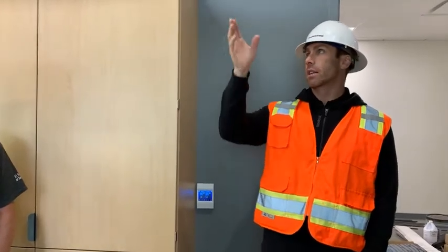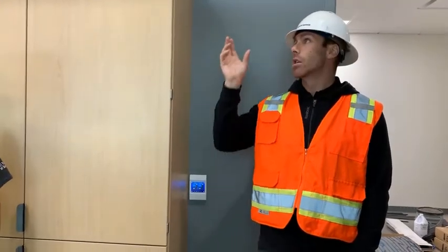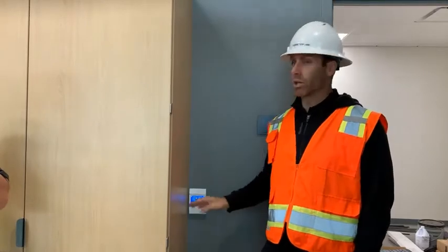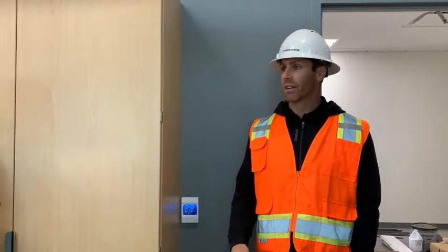I understand, usually these 2x2s or 2x4s, they're all intelligent fixtures. Okay. You hit off, you still have voltage there. Doesn't matter what you do with the switch. Off as many times as you want, you still have voltage to that switch. That's really important from a facility standpoint to know that. I know you guys should all be turning off the breakers, but just warning you. All right.